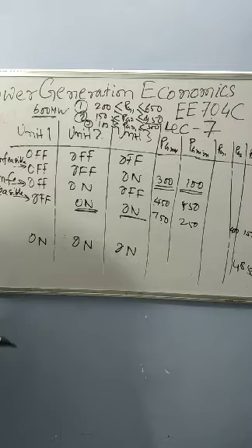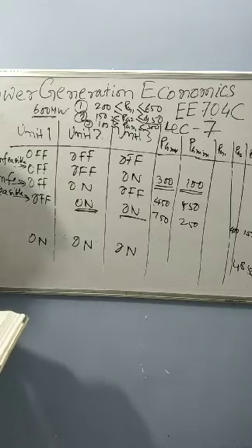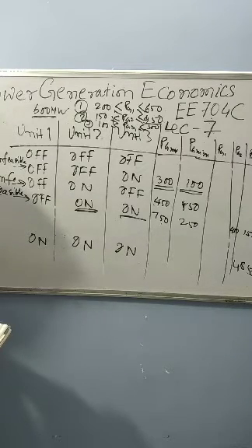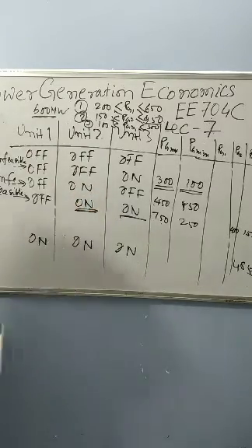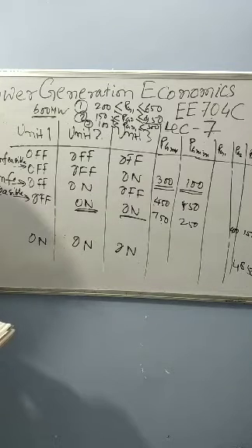But this is also not feasible. Why? Because the least expensive option was not to supply the generation with the three units running, or even any combination involving two units. So I can't take 2 units at a time or 3 units at a time. Rather, the optimum commitment is to run only unit 1.